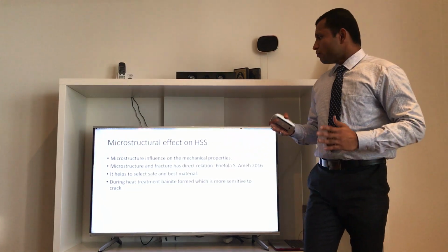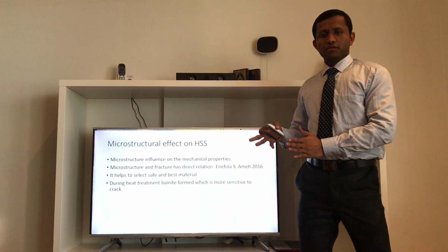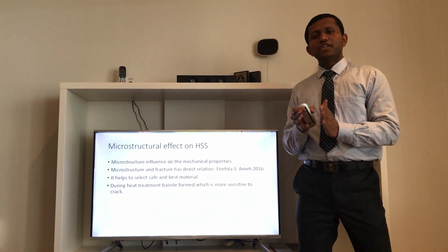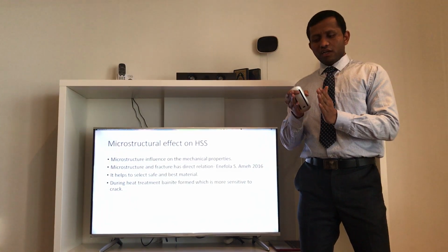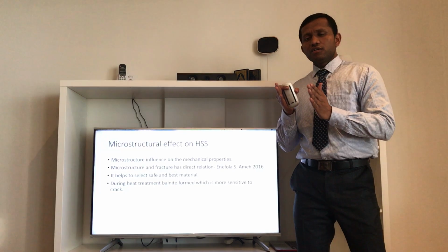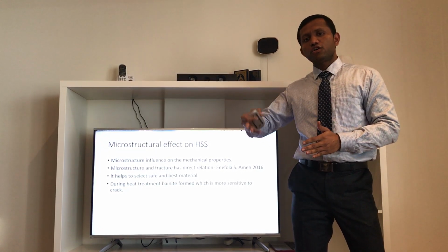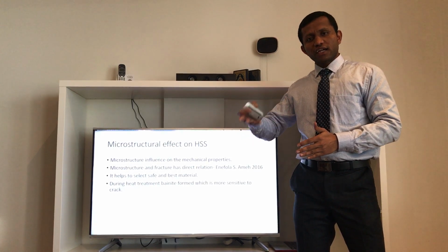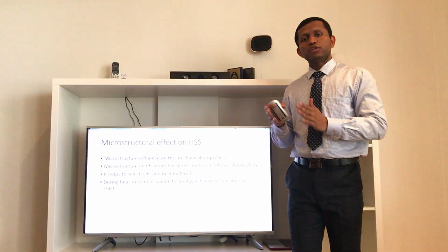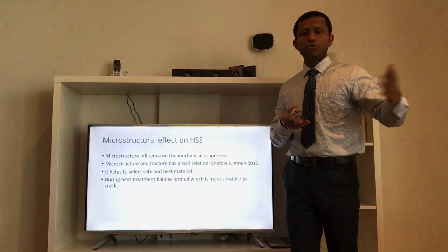So microstructure influences the properties of material. So if the microstructure is not proper, it can lead to the failure. Means while giving the heat treatment to any specimen, if the heat input rate is not constant, it can lead to the generation of pores, intergranular ferrite, and so many internal structures or grains which cannot be refined and make the structure fail more easily.